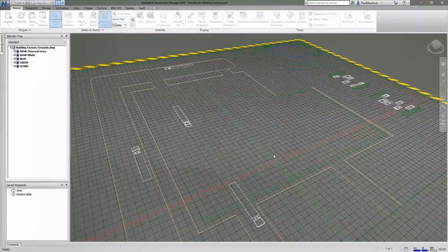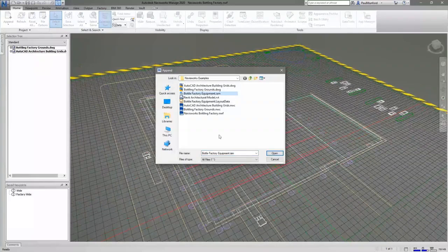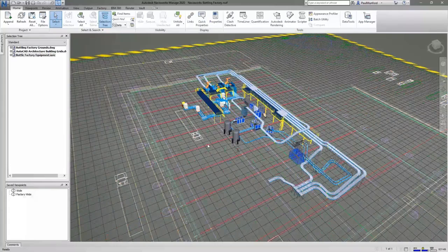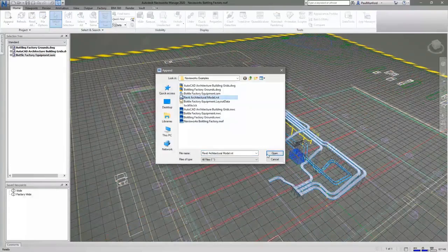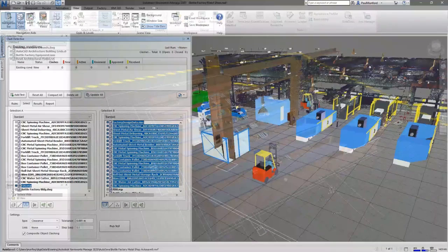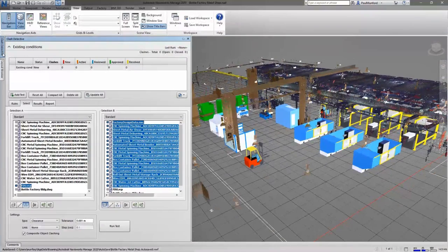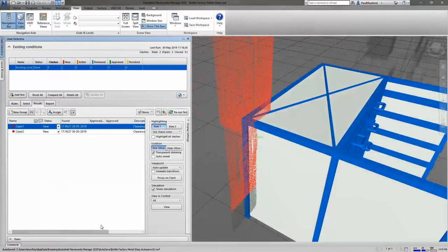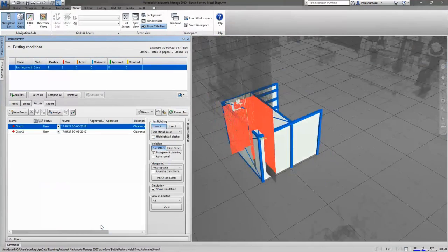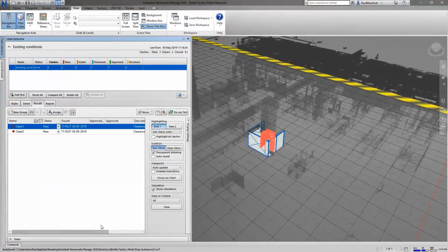These point clouds can then be inserted into your Inventor assembly, enabling an understanding of how the new and existing conditions work together. One of the core capabilities of Navisworks is the ability to collect all of this data together in a single environment. From your 2D layout, the many different 3D disciplines, and the various point clouds. You can then set up clash detection between all the geometry, and reports are then shared with all the relevant disciplines before making any of the necessary changes to ensure a smoother project delivery and installation.